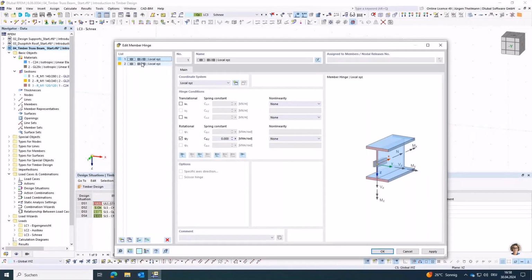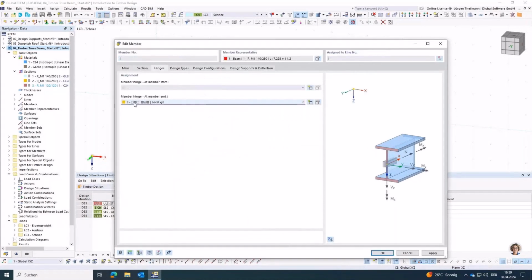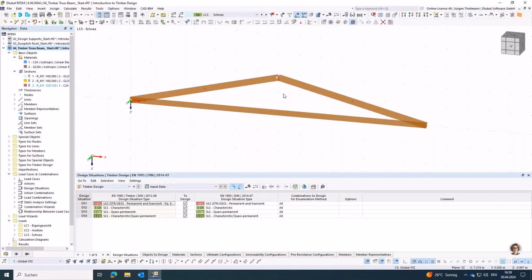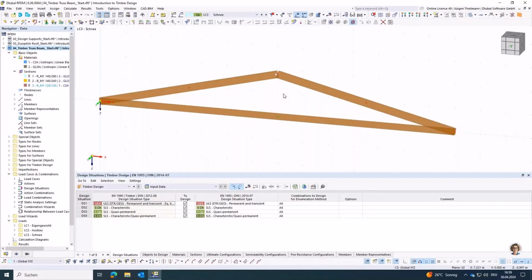This is the typical moment hinge, which I want to use. And don't worry because they are grayed out. This is just because this is now a 2D model, not a 3D model. Okay, at the end we have our newly created member hinge. I say okay, and I do this only on the left part of our upper girder because if I do the same on the right, we would create a hinge chain which would be an instant instability for all load cases, which we don't want and in reality don't have.